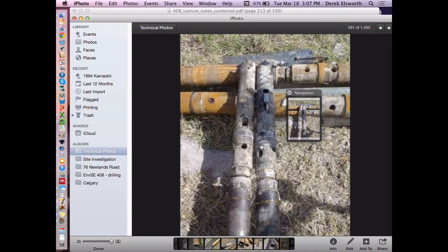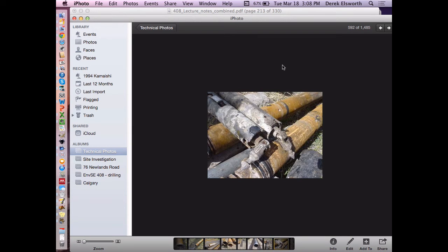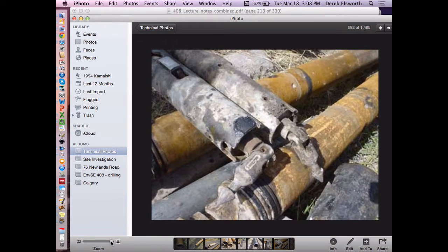This is all gimbaled, so it's linked. This little thing here that you see bent over would actually be sitting up. And so this little conical thing is the thing that the fishing tool latches onto. It grabs onto it, and it physically pulls the whole assemblage up through the top of the hole. You can see it here. So the fishing tool latches onto this and pulls it out. So obviously in doing that, you're able to get the core.